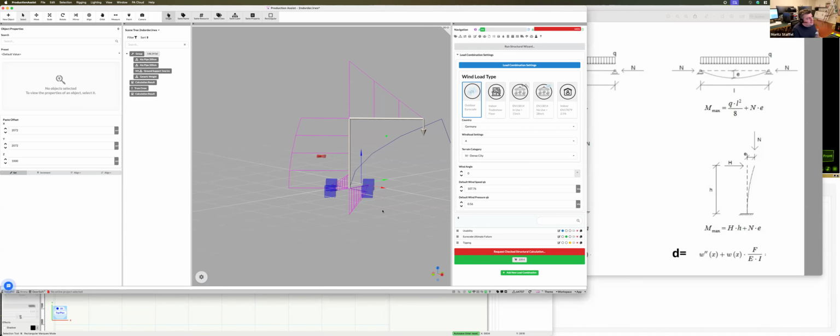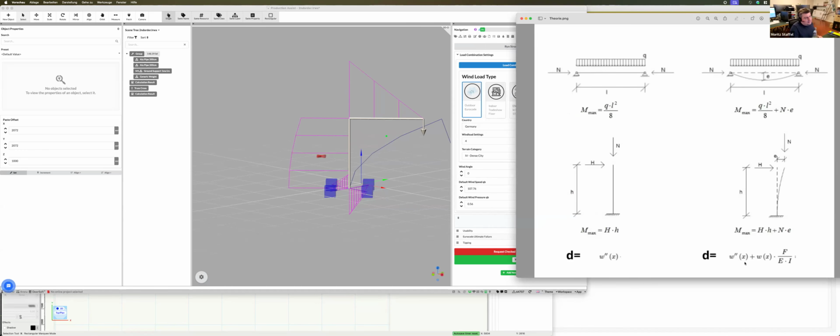So if you double the force, the resulting deflection will also be doubled. In the second order calculation, this is not true. If you double the force, you need a complete new calculation because the deflection also has an impact on the forces. So it actually uses a little bit different math in here.